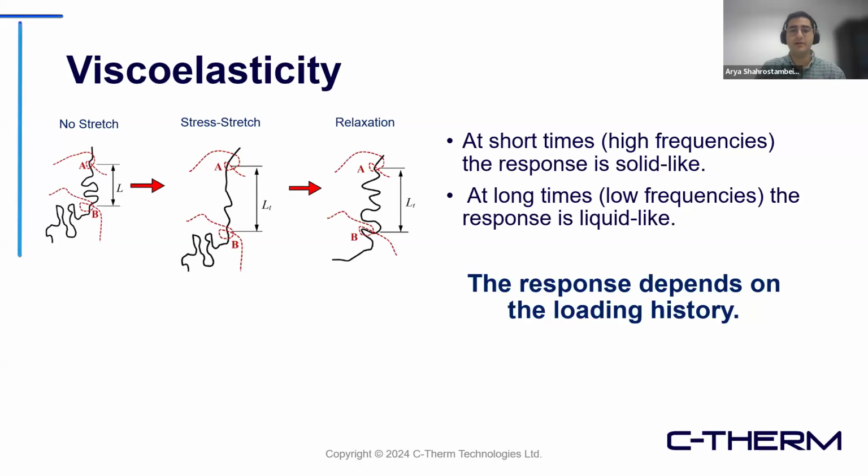However, it is very important to be aware that there is a relaxation time going on here. What does that actually mean? It means after you release the force or deformation, your material does go back to its original shape, but not instantly. There is a specific amount of time it takes for your material, which is called relaxation, to go back to its exact original shape.